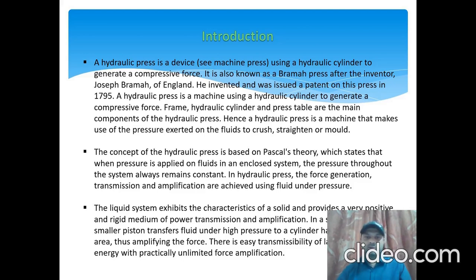Frame, hydraulic cylinder, and press table are the main components of the hydraulic press. Hence, a hydraulic press is a machine that makes use of the pressure exerted on fluids to crush, straighten, or mold. The concept of hydraulic press is based on Pascal's theory, which states that when pressure is applied on fluids in an enclosed system, the pressure throughout the system always remains constant. In a hydraulic press, the force generation, transmission, and amplification are achieved using fluid under pressure.